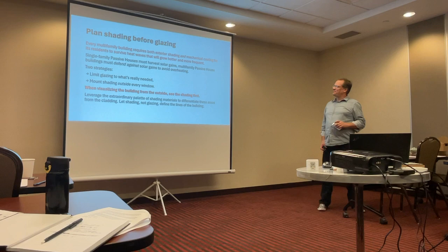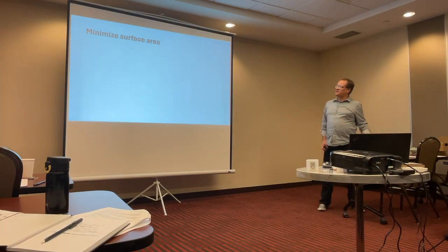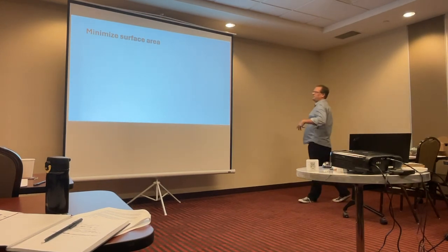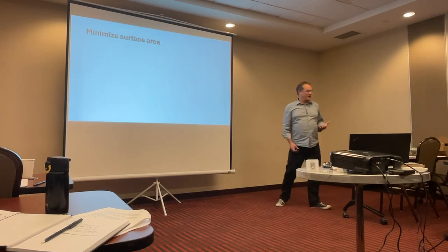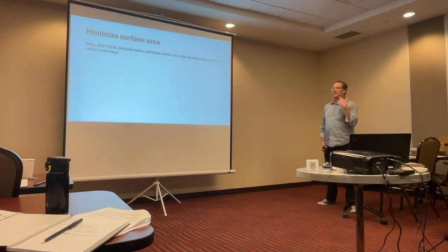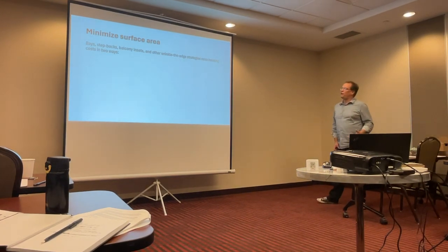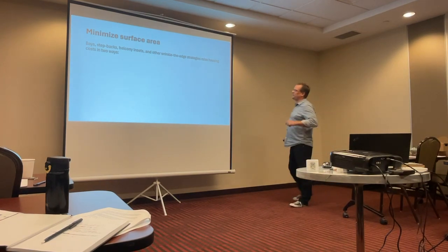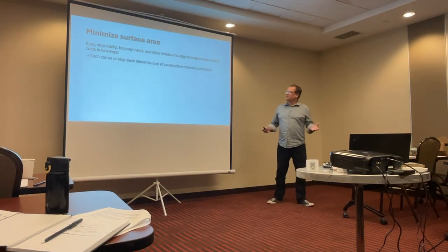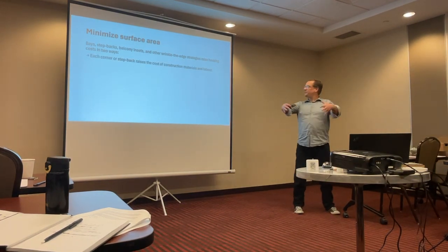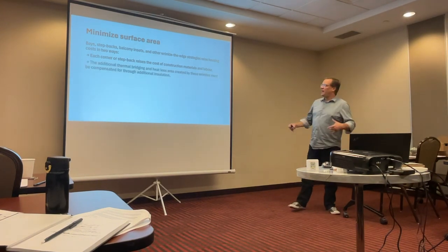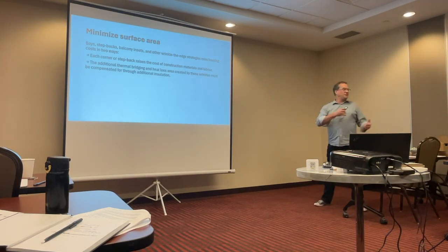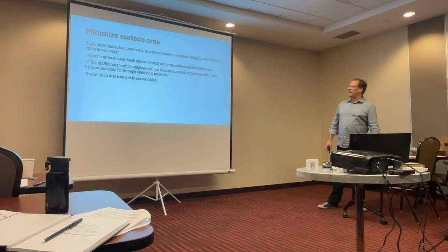So, we're going to come back, and then we're into design strategies here. So now we're really into chapter 2. That was some in the book, we're going to precede chapter 3 and 4 of it. You guys all know this. I'm struggling to find the right words and graphics to put it together, and I welcome feedback on graphics especially. But we all know bays, setbacks, balcony insets, and these other regulated strategies raise housing costs in two ways. You have that extra construction labor and material, and you have the additional thermal bridging that causes you to make up for it in some other way.